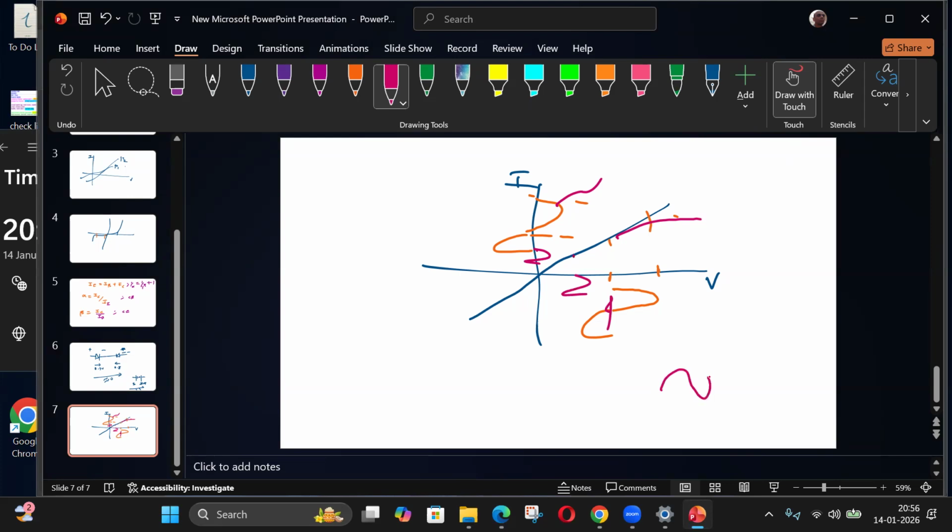So you can apply AC voltage like this. This is zero, this voltage. I can apply AC voltage, I can also apply AC voltage like this, where there is variation along with this bias. Suppose this is 5 sine omega t. This voltage is 6 volts plus 5 sine omega t. This is just 5 sine omega t. This is without the bias, this is with the bias. So this bias makes me choose this point properly, about which I can give the variation.